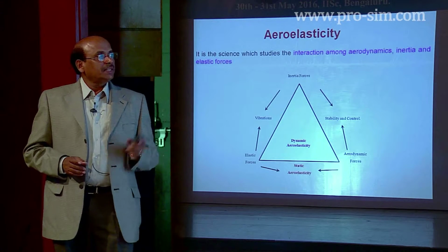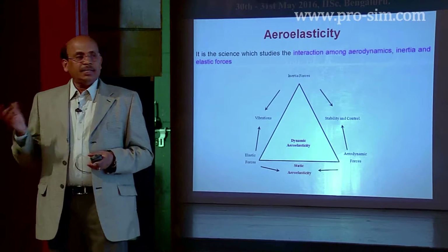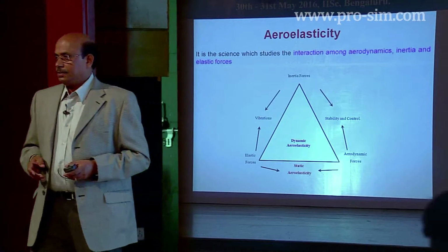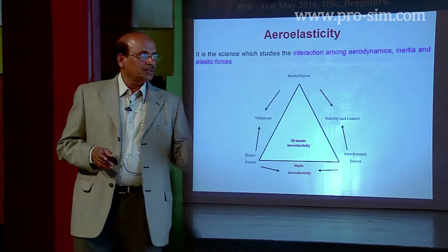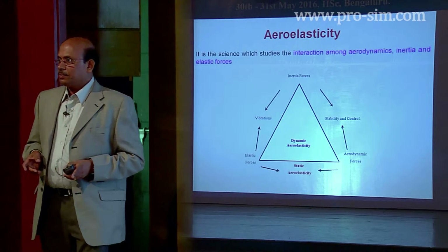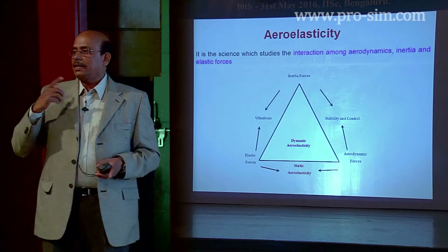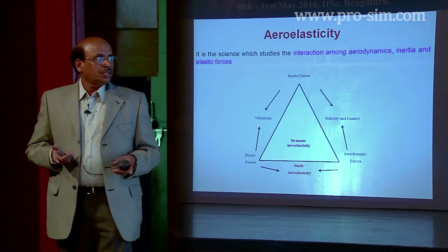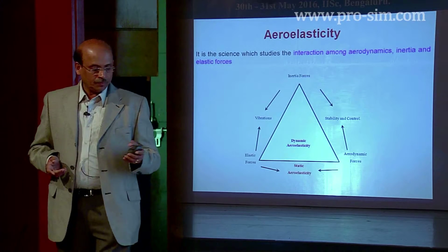The interaction between the inertial forces and aerodynamic forces leads us to the problem of stability and control of aircraft. The interaction between the elastic forces and aerodynamic forces leads to what are known as static aeroelastic problems. And when all three are interacting, it leads to the problem of dynamic aeroelasticity.